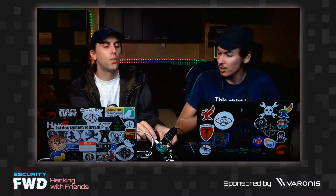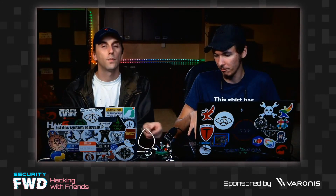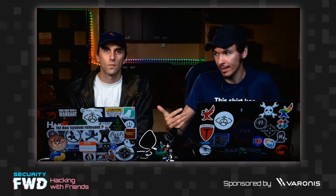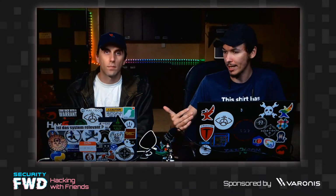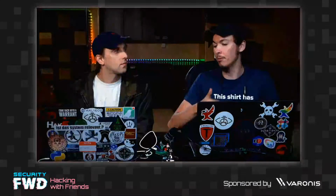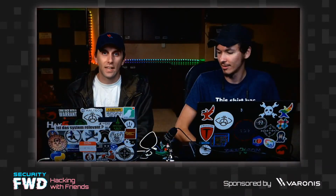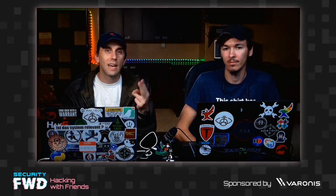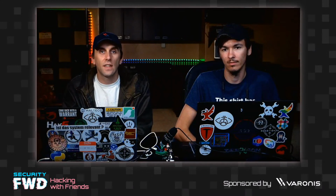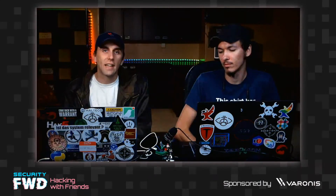So just to be clear, essentially what this device is doing is it monitors the Wi-Fi networks. And since these are unencrypted and unauthenticated, that means that anything can passively listen to them and read them fully. So it's able to just passively listen for these, even if it's going to a network that it's not connected to. So basically what the code that we're working with today is doing is it's listening for these two types of special packets that aren't used very often. And if we see that suddenly there's a large amount of these packets flying around, it's going to turn on these lights.